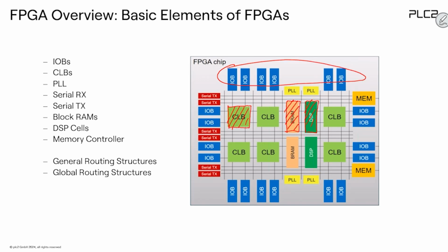Some of them are general-purpose IOBs, but some have special use cases, maybe serial high-speed transmit and receive, for example. Also, in order to support interfacing to external DDR memories, we usually have a memory controller, which is also implemented inside the FPGA.